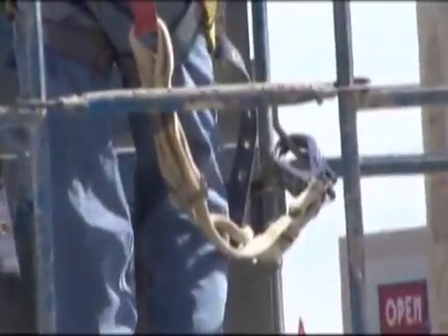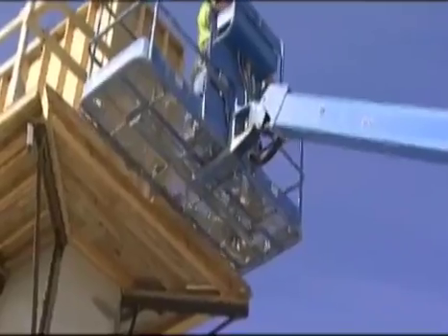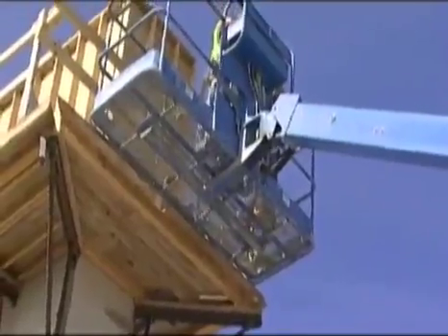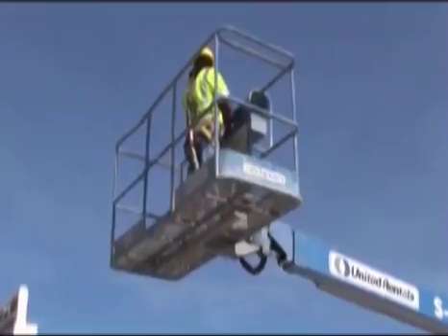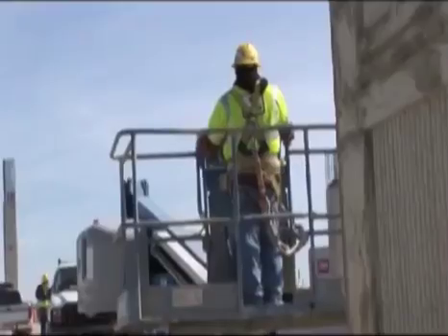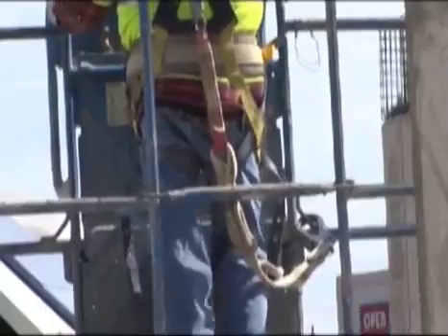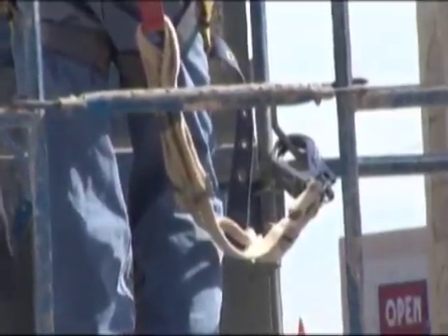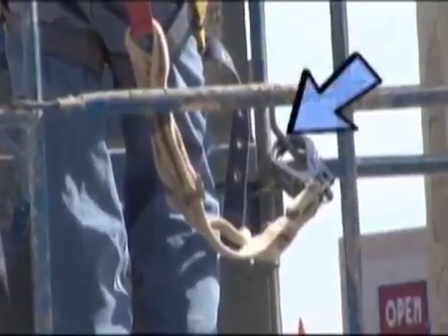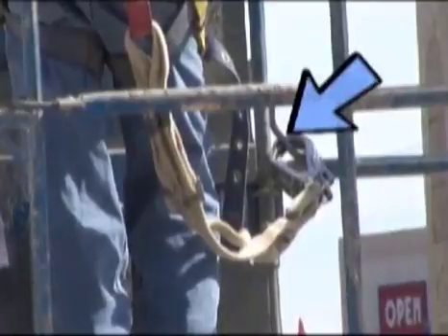All aerial lifts require fall protection. Guardrails and buckets provide some fall protection, but due to the catapulting characteristic of lifts, it is necessary to have additional fall protection. A full body harness should be worn and a lanyard attached to the boom or basket when working from an aerial lift. The length of the lanyard must conform to the lift manufacturer's guidelines. Most lifts contain a restraining point which is designed to attach to a personal fall arrest system or restraining device.